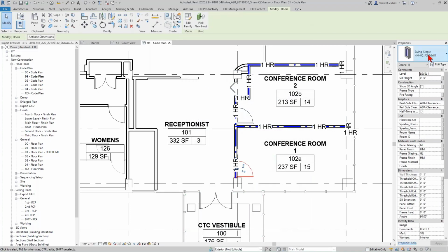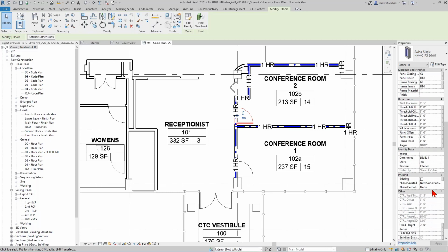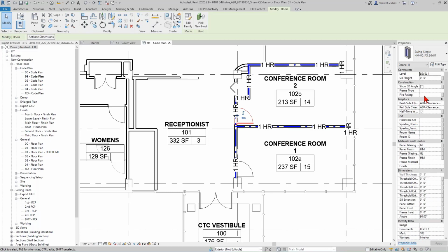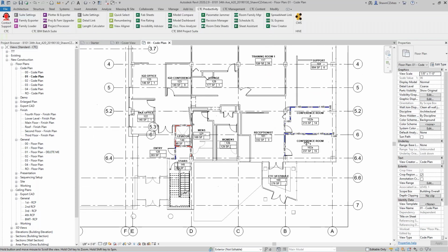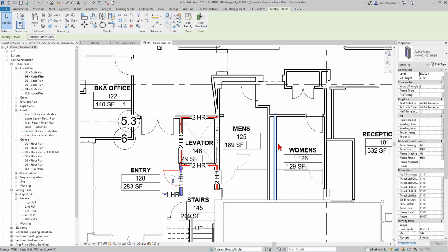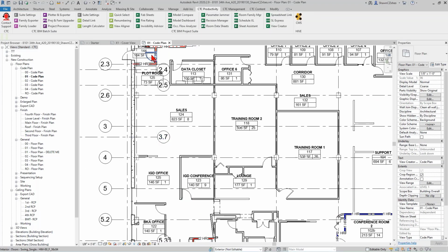These doors here are full glass doors, FG. That means that these two doors here should probably have a 45-minute fire rating. And right now, if I go take a look at the fire rating, it's nothing. Out here, I have another door that's in a 1-hour wall. This has glass as well, so it should also be a 45-minute rated door.